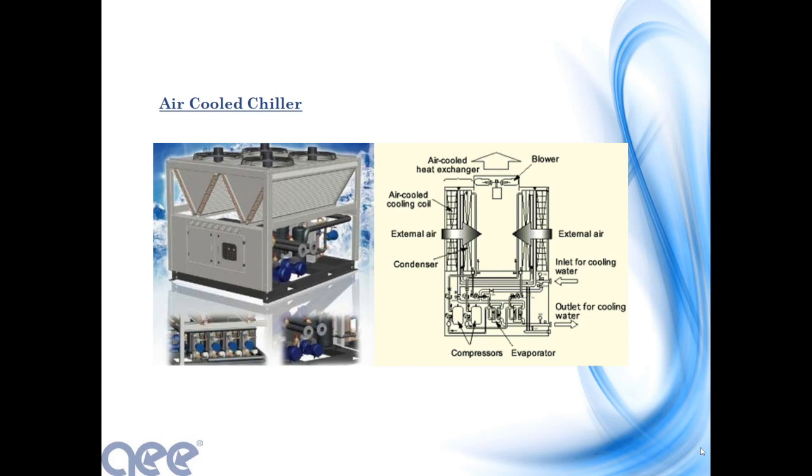So you have everything here that you have in your cooling tower and in your compressor, in an air-cooled chiller. If you look at a cutout of an air-cooled chiller, here are your compressors, right down here. That's what compresses the refrigerant and shoots it up into these coils, where a fan on top pulls air through the sides and cools the refrigerant down. These are your condenser sections, where you take outside air directly over the refrigerant to cool it down, and then it comes back down into the compressors again.